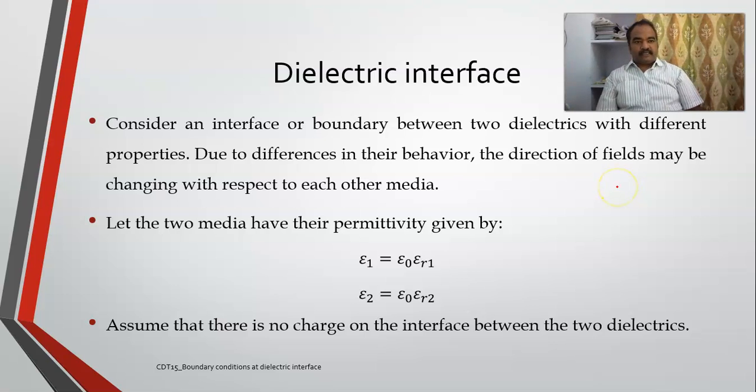Most of the times in electrical engineering, we don't use a single dielectric medium. We do use combinations of dielectric mediums. Let us suppose there is a long copper wire, or maybe an aluminum wire. Normally it is a practice that we will cover it with some sort of dielectric material, but there may be an additional coating over this one. You take any underground cable, generally it will have 3 to 4 layers of dielectric materials bound around it. Each of these dielectric materials will have a specific purpose.